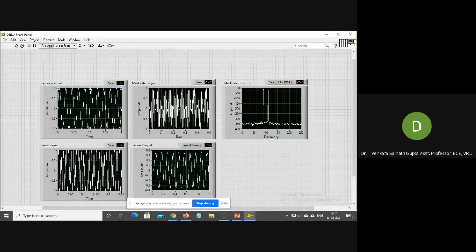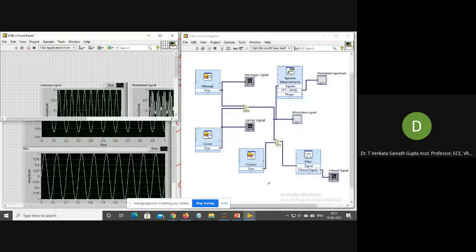One important point is there is no need of any Ka because your equation doesn't have any K. DSB-SC generation is very simple. You just need to multiply message and carrier. That is the reason we don't have any Ka here.